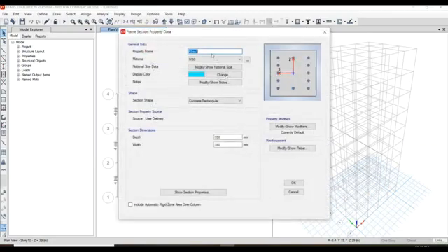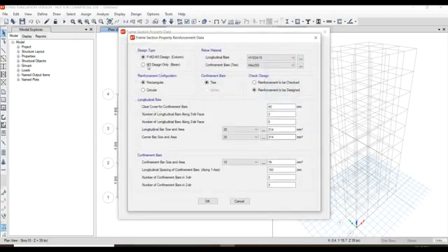Also click on the column 350 by 350 just created and add a copy of the property, so that for ease we can add a beam of 350 by 350, or else we can change to any other name as we wish. Take M30 from the drop down, and depth and width are 350 and 350, as we made a copy of the property. Modify the rebars.